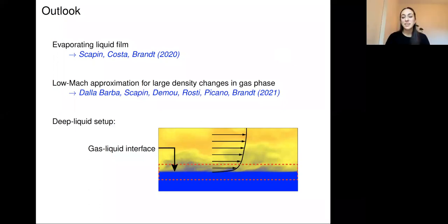Does it influence your breakdown process? We haven't studied that. That's a good question. I think the other effects are bigger, like the film thickness and the Reynolds number. Those change it more, because it takes a little while for these deformations to even happen, so that very first condition changes quite quickly. The real deformations don't come out that quickly from the turbulence. We haven't studied that in any systematic way, but I shouldn't think it would be a big difference, especially compared to the other effects that we have here.